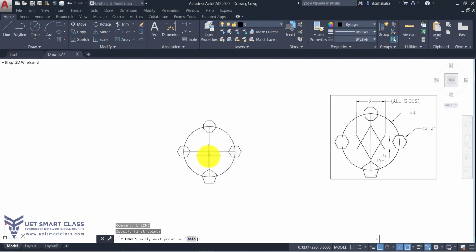So I'll show a distance in this 270 degree as 0.5 and click enter. On this 0.5, I'll show 1 on 180 degree and again come out of the command and again press, because I cannot draw in continuity. I have to come back to the center point, and this side also 1. So now I've got my edge. Same way I'll do the same thing. Upside 0.5, then going towards 180, 1, and then coming back and going towards 0 degree, 1. So I have my 2 sides.